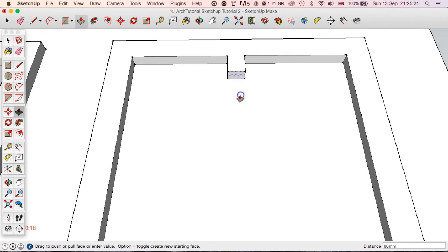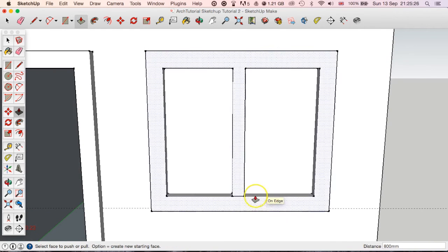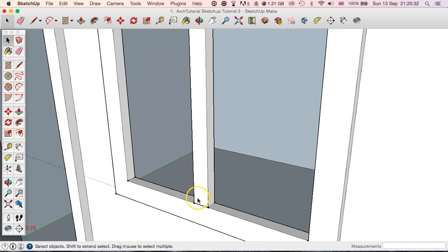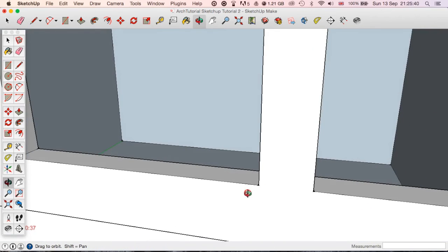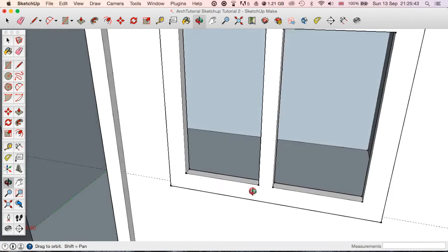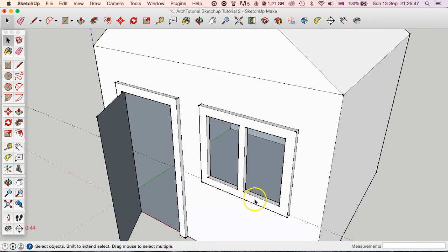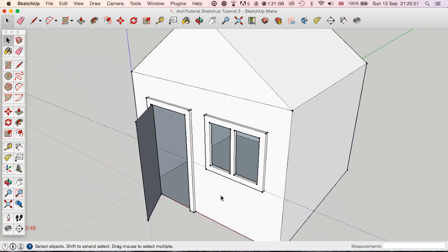What you can then do is extrude that box down and snap it. So now when we delete these 2 boxes, you can see we've got that center part. What you can also do, to make it more integrated, is delete that line. Therefore when you're applying a material to it, which we'll come on to a little later in the tutorial, it will automatically do it to the whole thing. You wouldn't have to apply material to more than one face.